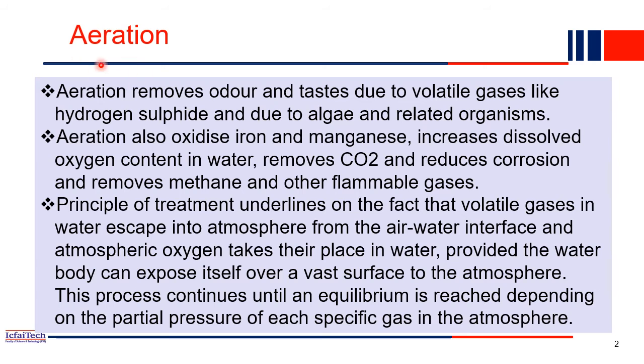But basically aeration is a process where we are removing the odor. Odor means if any smell is there on the water, that will be removed. And if any volatile gases are present in the water, like hydrogen sulfide or many others, that will be removed in this process.